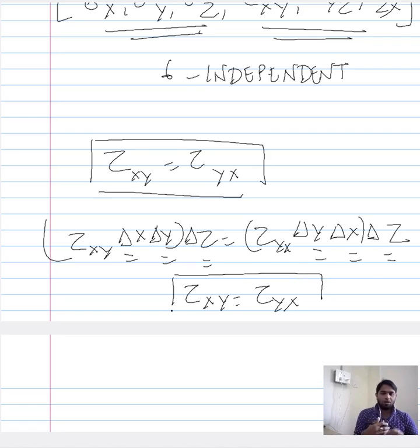So irrespective of how you arrive at this equality, what we now know is that when you have a 3-dimensional system experiencing triaxial loading, then to define the mechanical condition experienced by a point within that system, you need 6 independent components, and if you want the maximum number of components, then it is 9.